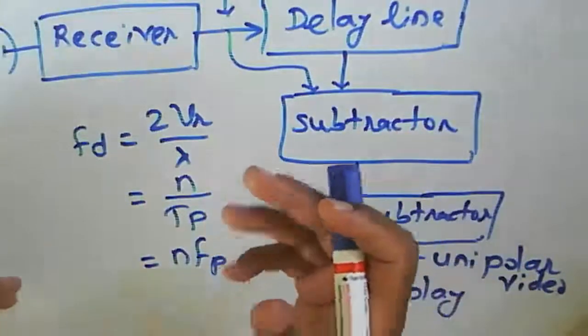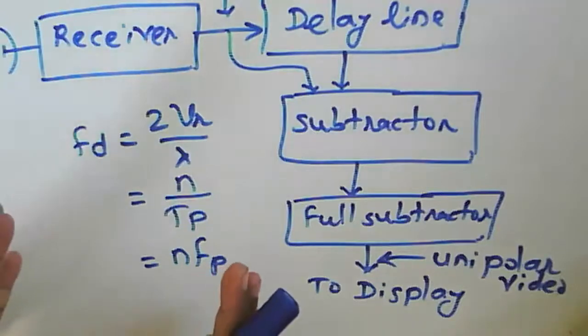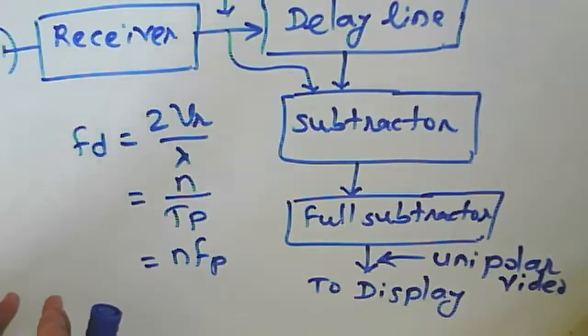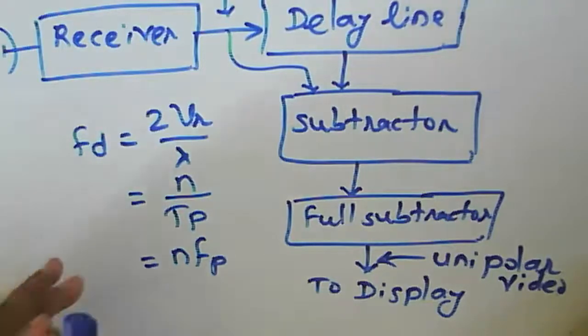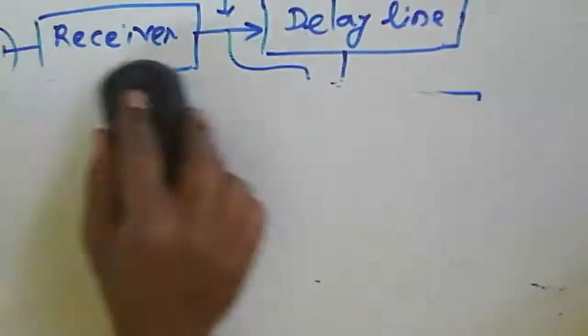Okay, that's why we are getting the blind speed. Generally, if you see this delay line canceller, it is just rejecting the stationary clutter at zero frequency. If the target's pulse repetition frequency is the same, then your response will be zero. And this delay line canceller operates only in the time domain, so that's why it is called a time domain filter.